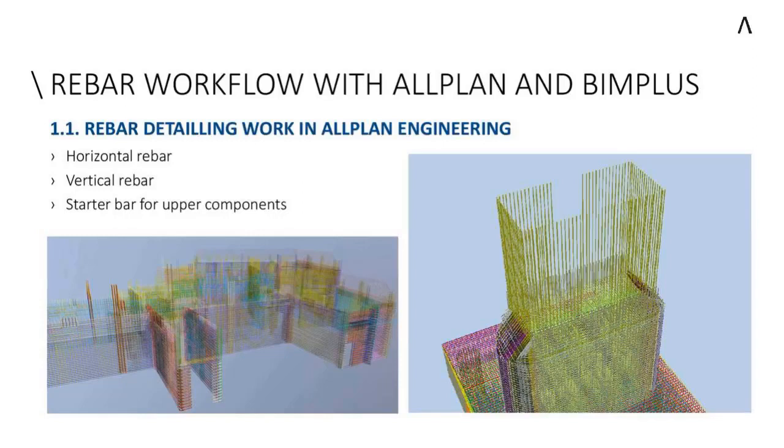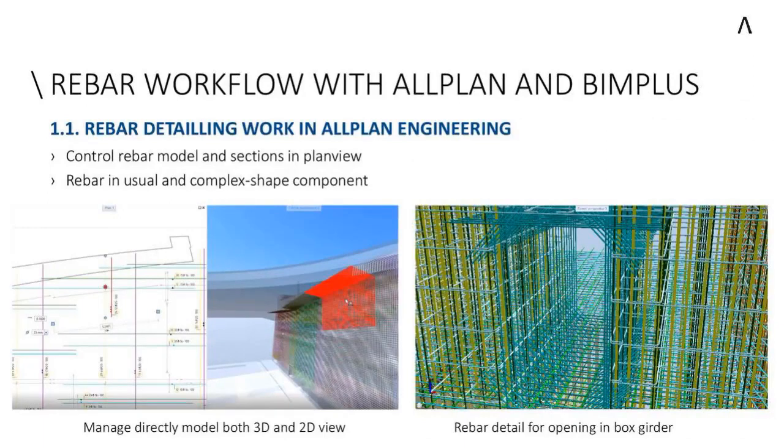And for a typical foundation here for a bridge, you can create it. And for a more complex component, you can see this is part of a tunnel. You can control the rebar model in section and plan view, and at the same time you can see which rebar we are working with in the 3D view. In that way you can create the whole rebar model very easily, like in AutoCAD, so it's very convenient.